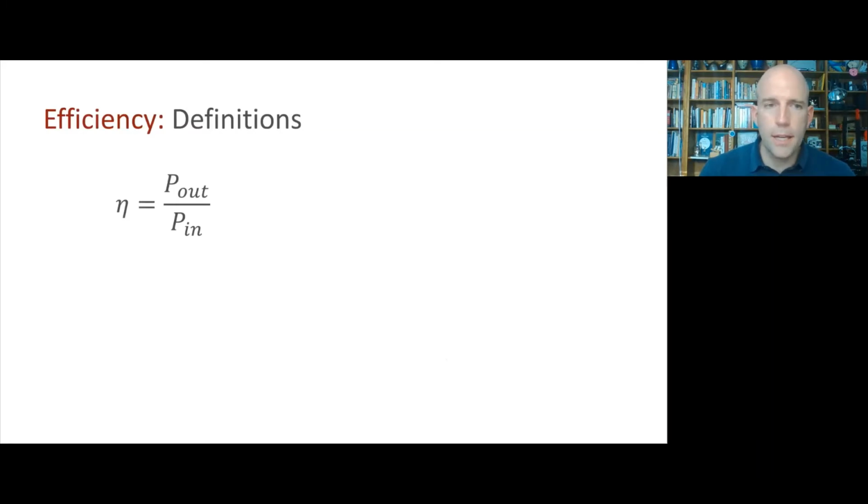So the last thing we're going to try to estimate for our system is the gearbox efficiency. And we're also going to use efficiency thinking for some of our calculations later. So let's dig in on this from a high level. The first thing to remember is that the efficiency is the power out of the system divided by the power in. So you're going to pay some useful power into the thing, you're going to get some useful power out, and you're going to lose some power to, say, heat because of friction or heating the coil or something like that. And so it's just the useful power out divided by the useful power in.